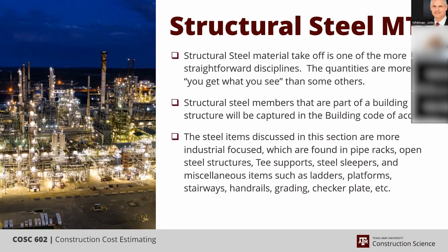Professor, I had a question on some of the concrete takeoffs, like for the foundations. In experience, when you have those small quantities, we didn't do it on ours as far as putting just 10 yards, because that's what a truck holds. We did a normal waste factor, but on some of the smaller quantities, I did put like a 10% waste factor, because they're such small quantities. Is that something you would do, if it's a small quantity like that? Because you're either going to have to pay a short load fee or just pay for a whole 10 yards. No, that's a very good point.